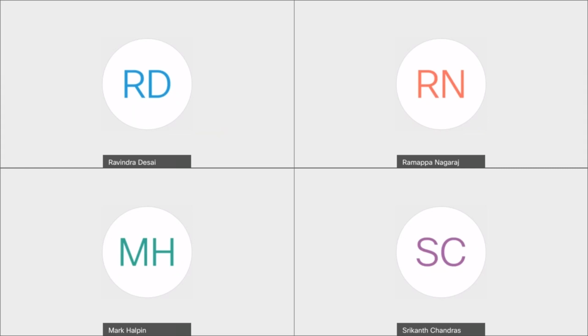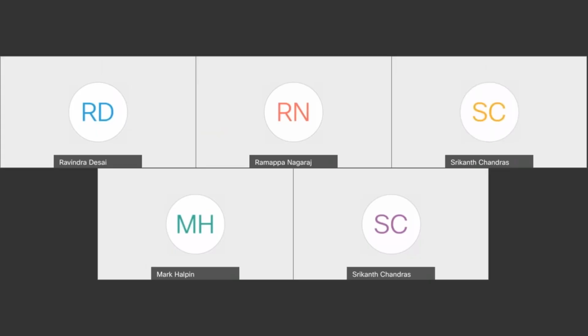Now let us see the balanced triplen harmonic. When there is a balanced triplen harmonic, basically I sin omega t for the R phase, for the Y phase I sin(3 omega t minus 120), so that becomes 360 and therefore it is again I sin omega t. Then for the B phase you have I sin(3 into omega t plus 120), again it becomes sin omega t.